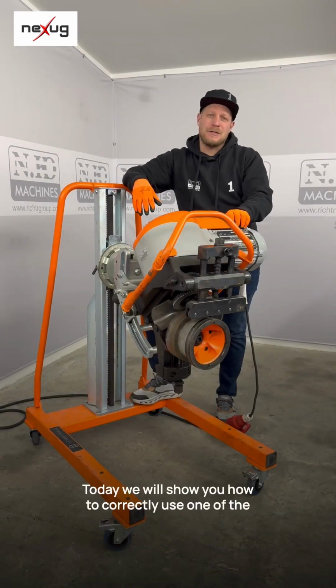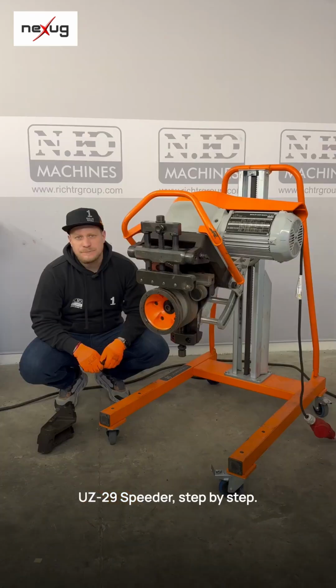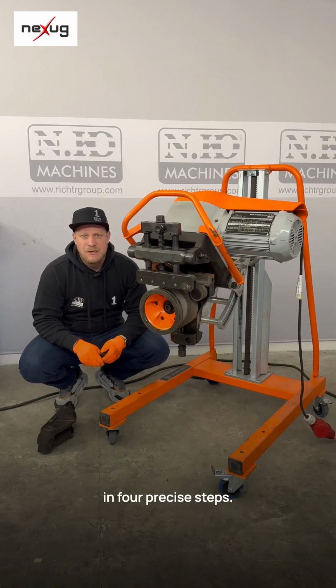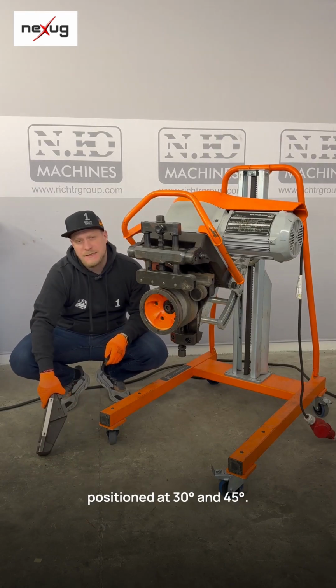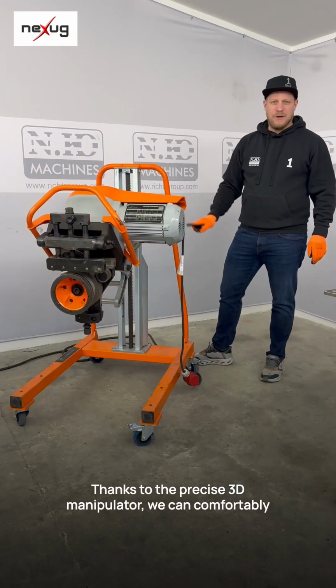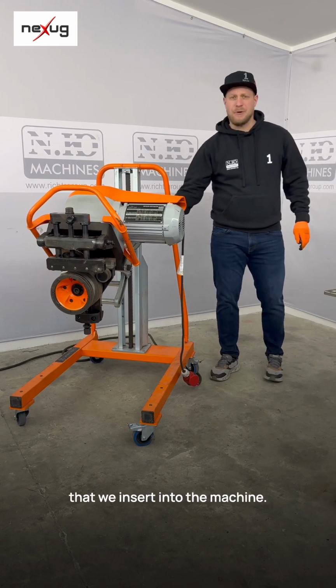Today we will show you how to correctly use one of the largest machines produced by NKO machines, the UZ29 Speeder, step by step. We will achieve a maximum bevel width of 29 millimeters in 4 precise steps. The machine comes with 2 angular arms, positioned at 30 degrees and 45 degrees. Thanks to the precise 3D manipulator, we can comfortably use the machine for both very long sheets and small workpieces that we insert into the machine.